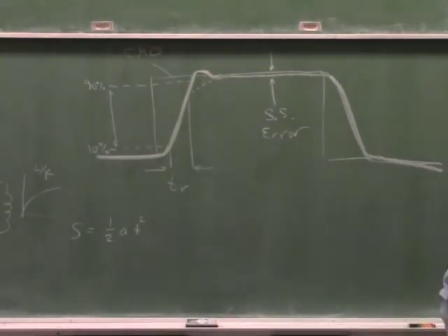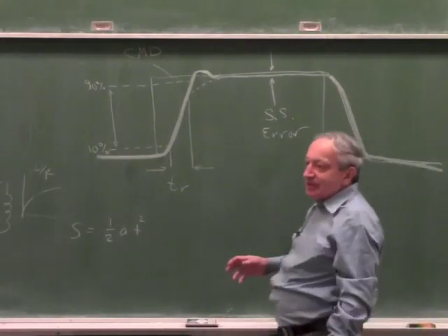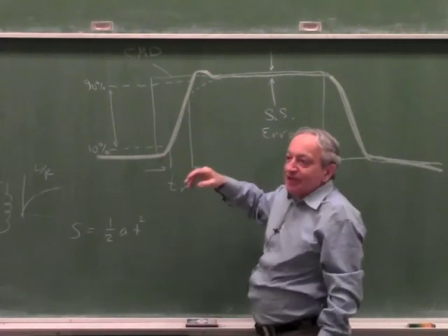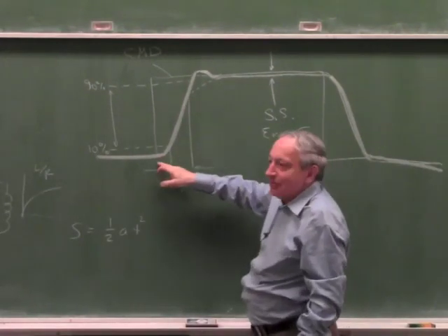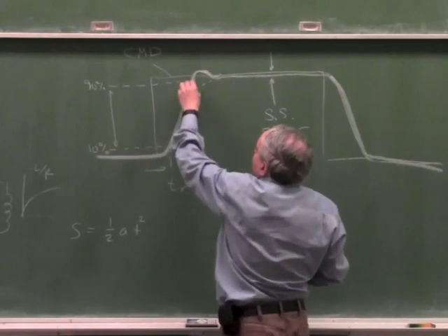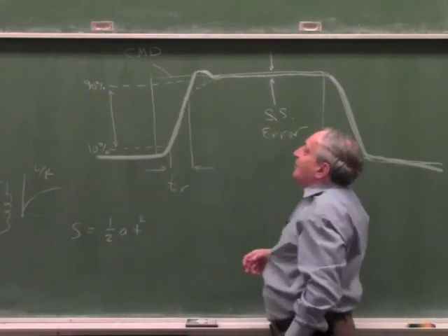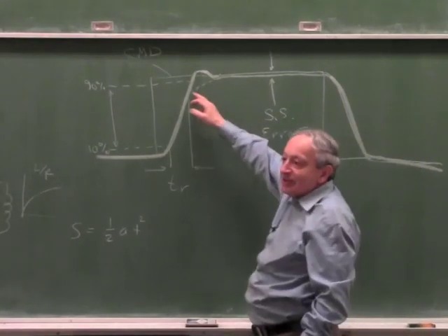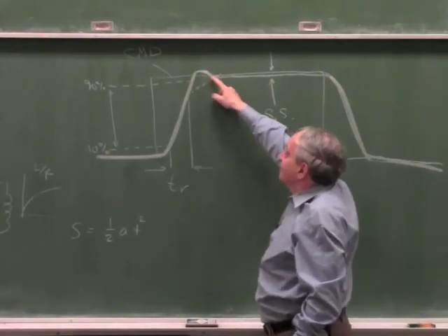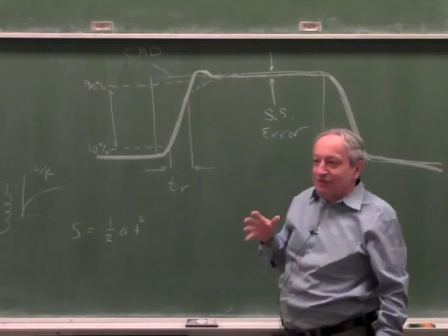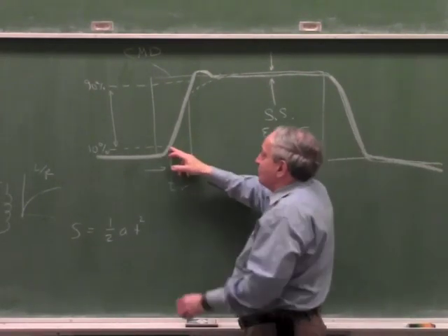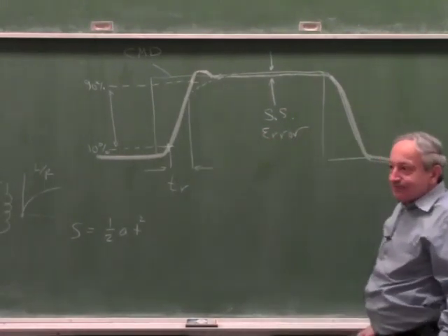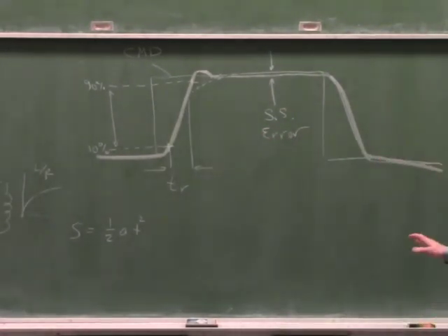Now, the reason why rise time is defined 10 to 90 and not 0 to full is because sometimes you don't see clearly what's happening here. If this is rounded and this is overshoot or undershoot, if you define rise time of the system by when it reaches 100%, some systems never reach 100%. Say they oscillate, so it's hard to define. It's easier to define at 10%, it's already clear what's happening, and at 90% it's clear what's happening. Okay? So this is a typical servo response.